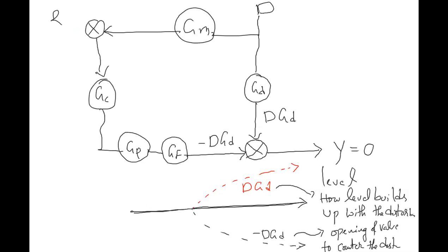This control loop is like this only. I'll tell you, as I said, this is slightly confusing. G1. This is my set point. So basically you follow this one. This is my disturbance. You are measuring the disturbance, that measured disturbance, and you have a set point. There is some modification here. We'll go to here, and then this will go to the controller. Controller will go to the process, and process will open the final control element. Clear? Or this will generally be the controller affecting the final control element, which affects the process. So this is something like this.